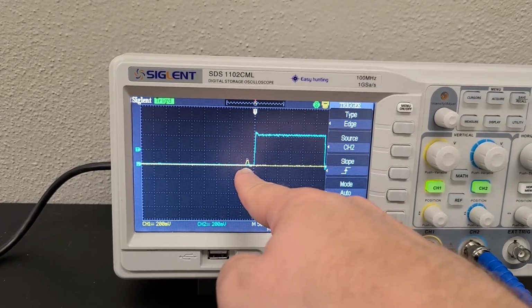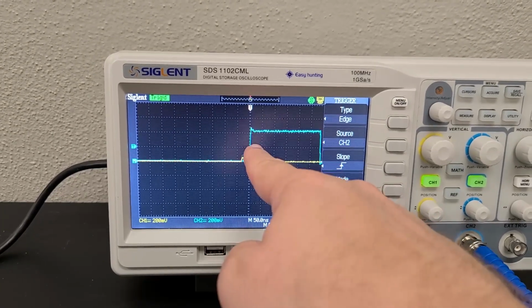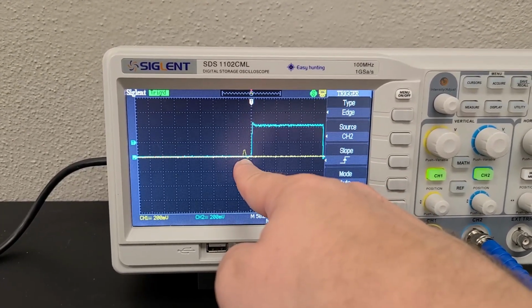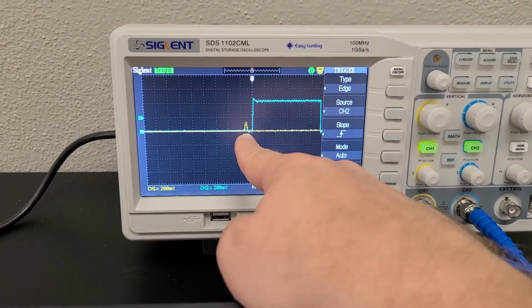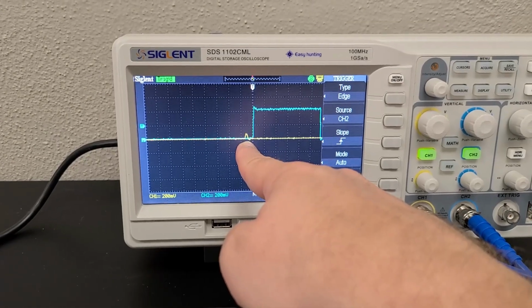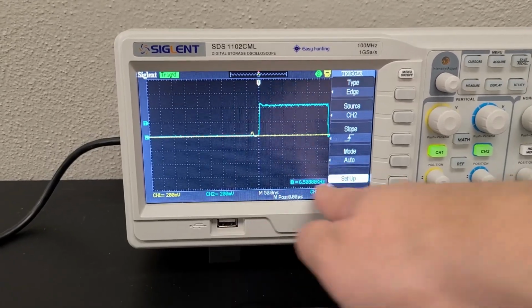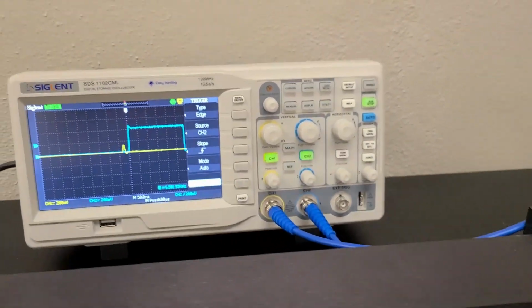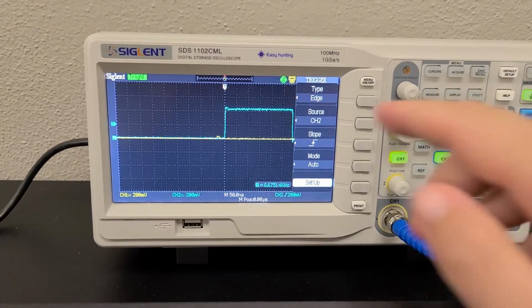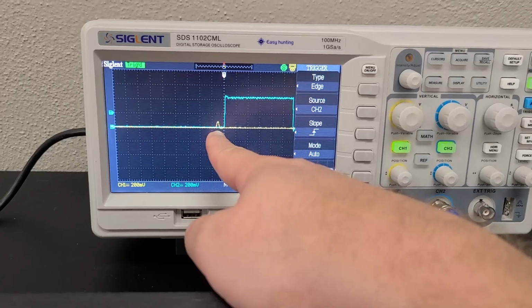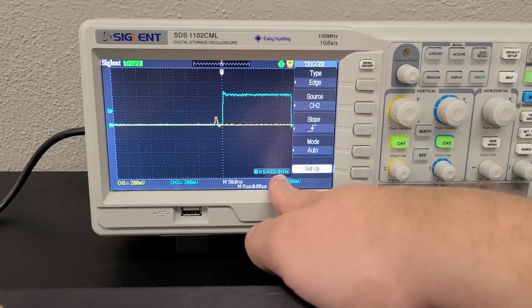So for every one of these signals that it gets, it sends one of these signals to the counter and counts it. Okay, but you can see that the amplitude of these is kind of crazy, right? It's counting very small noise oscillations and very large oscillations that are corresponding to photons hitting the PMT. So what we need to do is change the discriminator voltage on our counter so that it says, okay, if these incoming signals are not above a certain level, we're not going to count it. Okay, and we want to change that until our frequency is about half of what it is now.